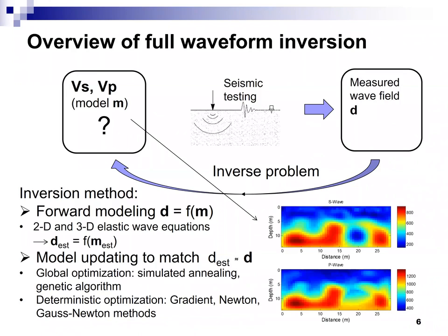Hereafter, I call that the model. So for site characterization, we divide the subsurface structure into several thousand cells and determine the VS and VP of individual cells. So we can build the S wave image and P wave image like this. And then we can identify the void, in this case inside the limestone, based on the shear wave image. So we are solving a problem of a few thousand unknowns for 2D, 20 to 30,000 unknowns for 3D, or even larger than that. So to solve the inverse problem, we need the forward modeling and model updating.